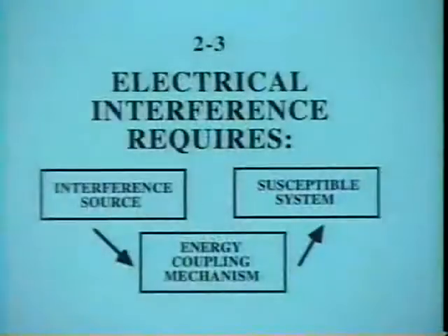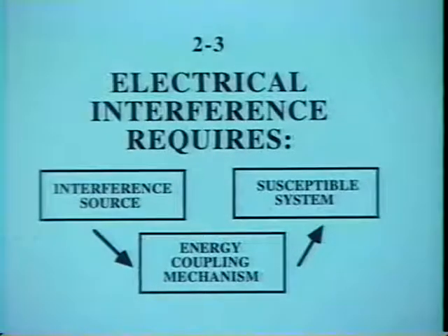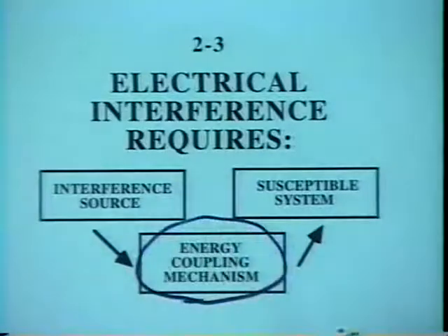Now, every noise problem has three basic parts. There's the interference source, the energy coupling mechanism, which we're concentrating on primarily in this session, and the susceptible system. The most critical part of this problem, I believe, as far as diagnosing and fixing it, is determining the energy coupling mechanism. If we know what that mechanism is, and we know where that process is located physically, then we have a very good chance of fixing the problem.